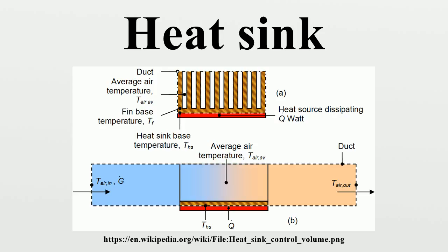The most common heatsink materials are aluminium alloys. Aluminium alloy 1050A has one of the highest thermal conductivity values at 229 W per meter K but is mechanically soft. Aluminium alloys 6061 and 6063 are commonly used, with thermal conductivity values of 166 and 201 W per meter K, respectively. The values depend on the temper of the alloy.